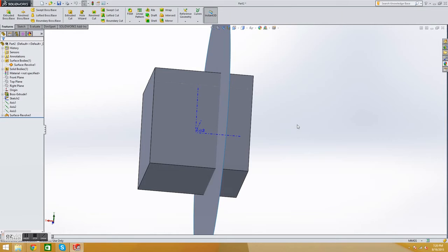Alright, so SolidWorks, this is the end goal. It has this cool feature where you take a surface, kind of like this surface, and you can take a body and you can split it along the surface, kind of like if this were a knife, and it'll split it exactly where the faces are. But if you just took this surface and you split it, that would just give you two pieces. That would give you this half, just like one layer, and then this half, which is like two layers, which we don't want. We want 27 pieces. We want 6 centers, 12 edges, 8 corners, and 1 core.